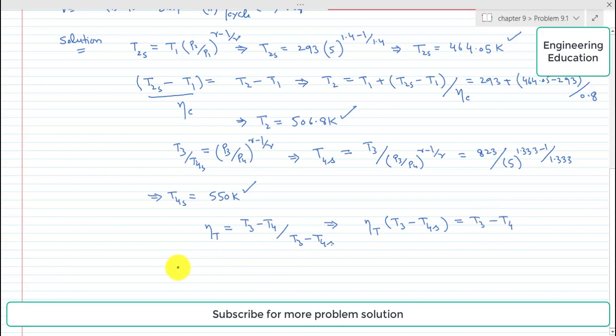So again rearranging this expression, T4 is equal to T3 minus turbine efficiency into (T3 minus T4S). So putting the values,